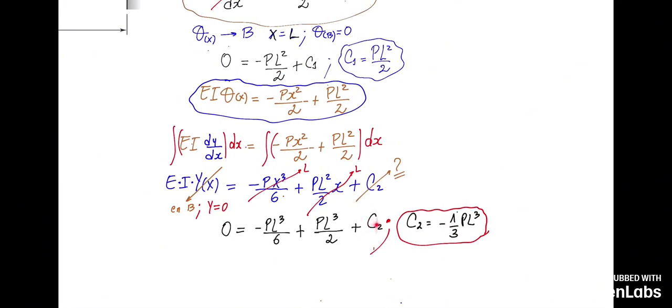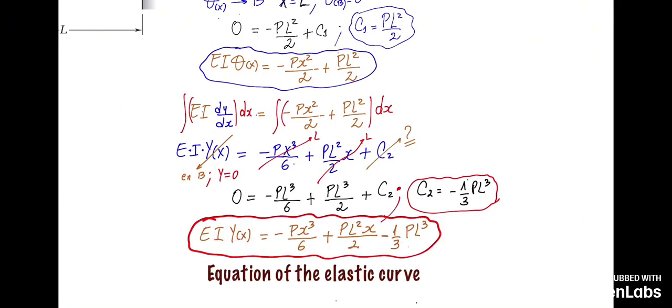And then, we have determined this integration constant, then we replace it here, and we will have the general equation for the elastic curve. And there is our equation. It is known as the elastic curve equation, or the equation of the elastic curve.